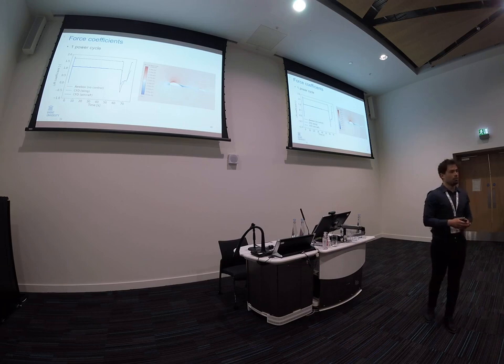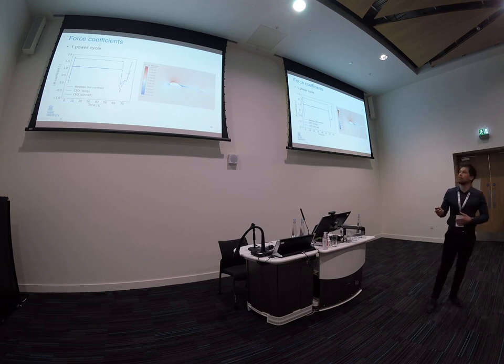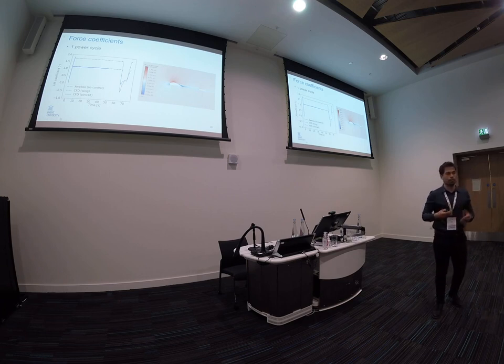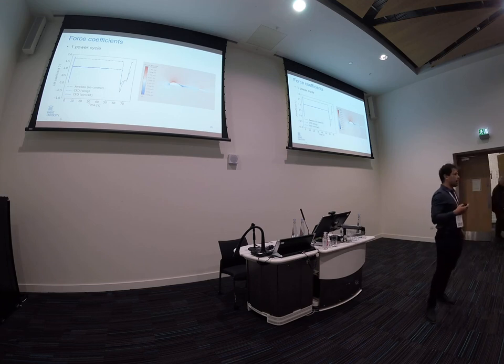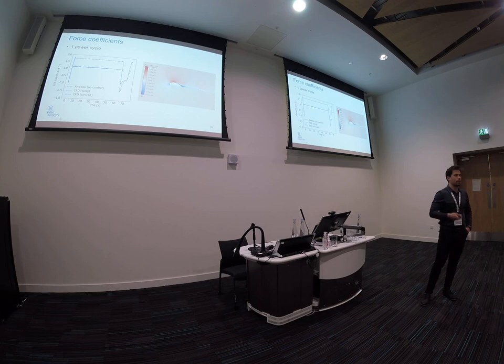A probable reason why we would predict less lift is that, if we look at the velocity magnitude, we see some blue zone here, which indicates that there might be separation at this operating point. Again, to really have proper results or to be confident, we need to do some more detailed mesh studies, but this already gives an indication of what's going on here.